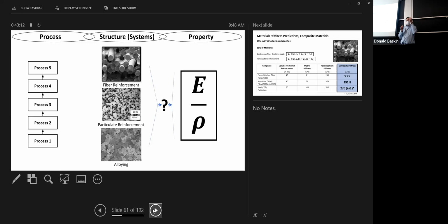That now means that you have stiffness that's different in three directions too. If you can measure the stiffness of that little crystal, you have different stiffnesses in each of the three directions, right? Because it's aligned. If you take gazillions of those little particles, you suspend them freely in a liquid, and you stick that in the magnetic field, all those little particles are going to line up with their B axis to face in the same direction.